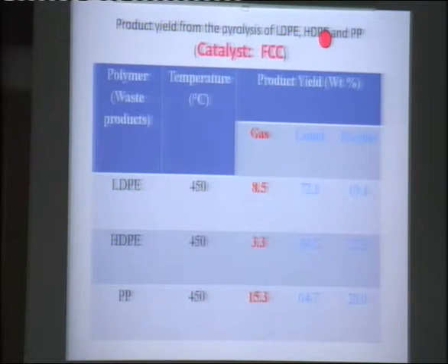You want to extract energy from these plastics, but because it is an endothermic process, you need to supply energy for cracking purposes. That is the reason that if you use a catalyst, you get several advantages. The cracking will occur at lower temperature, the rate will be high, and you will get the desired product if you use the specific catalyst.